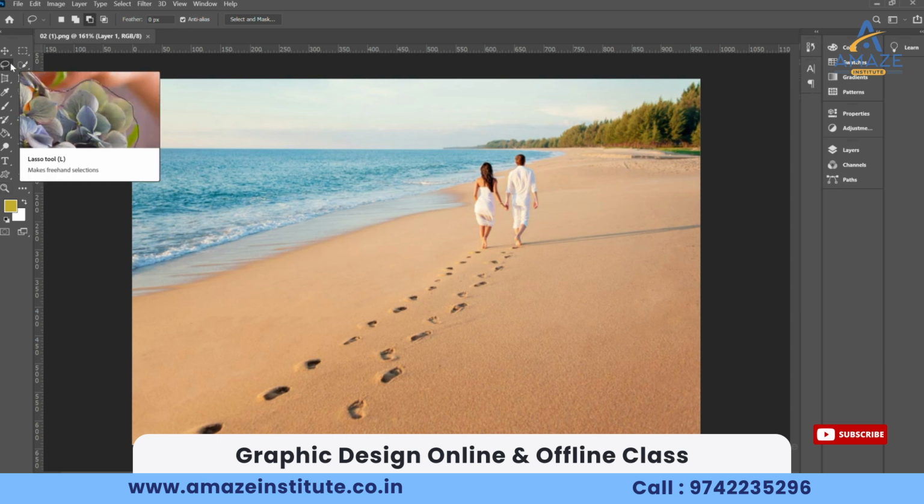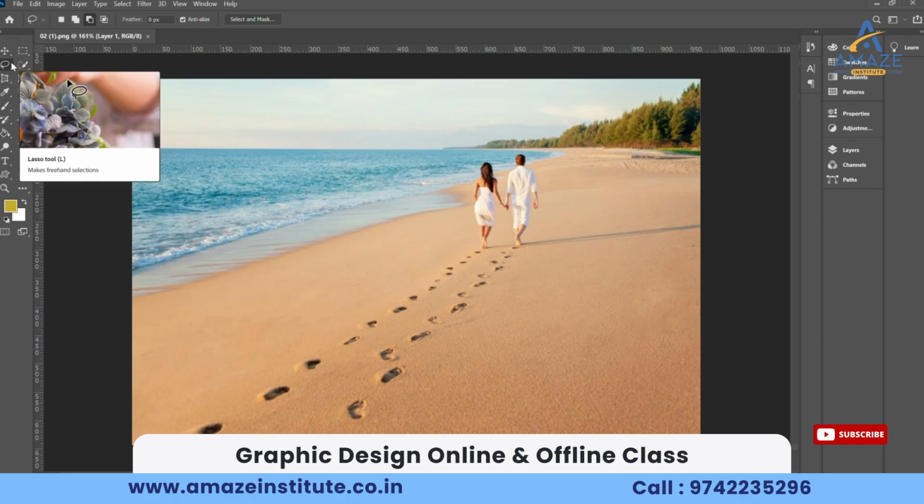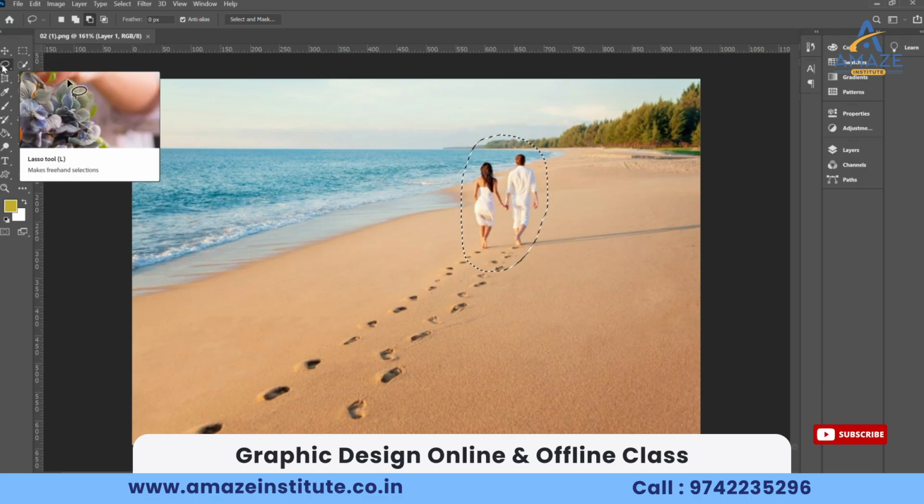The lasso tool was also in Illustrator, but there we use it for selecting shapes. If there are some shapes here and there, you can use the lasso tool for selection. The purpose of the lasso tool in Photoshop is also a little bit similar. I'll show you how. Now we selected the lasso tool, and if I draw around this object like this, the object gets selected. But if you want to make minute selections, we can use the lasso tool in Photoshop.